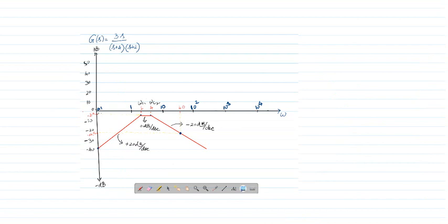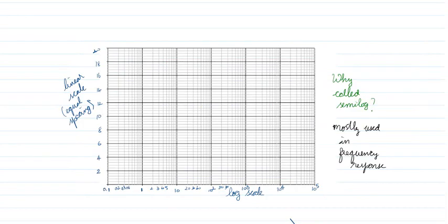We have already found the values, right? Before, I missed out a point, so look here very closely. The lowest frequency I am taking is 0.1. I should not take 0; we'll understand later why. Since it is a logarithmic scale, the next point is 10 times: 0.1 times 10 is 1. The next major line is 1 times 10, which is 10. Then 100, 10 squared, 10 cubed, 10 to the power 4, 10 to the power 5. Now, if this is 0.1, this is 1.